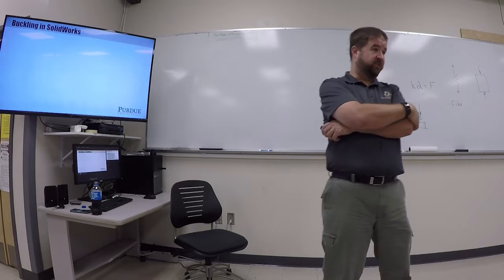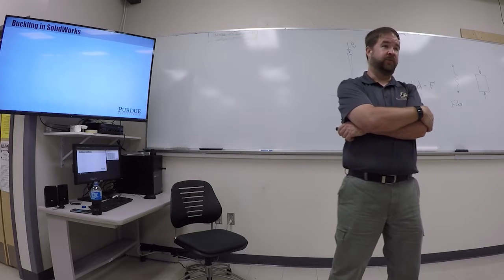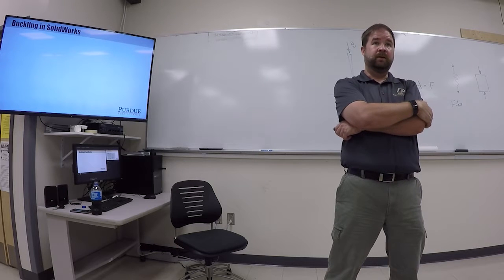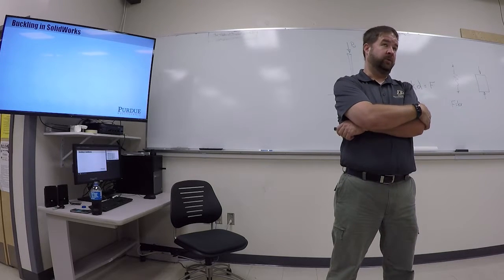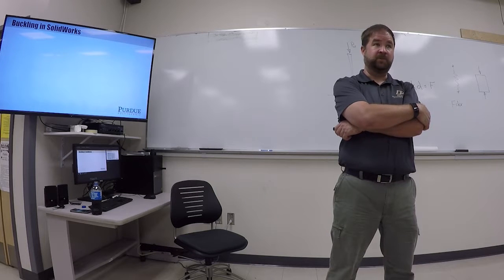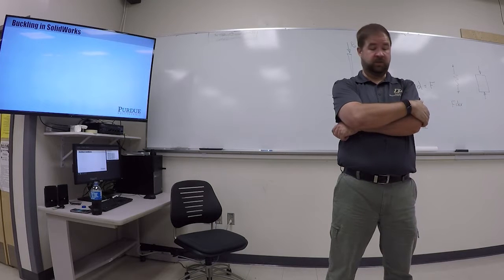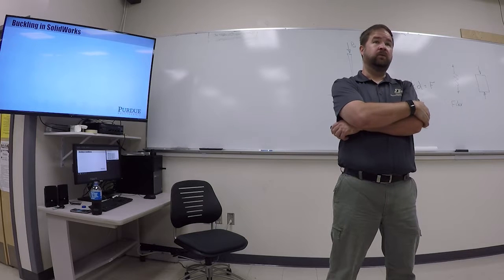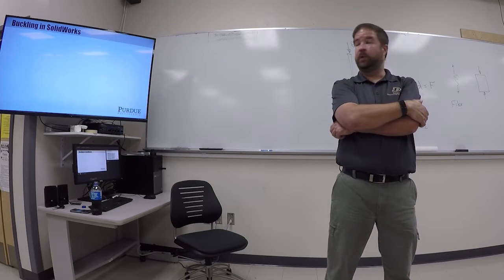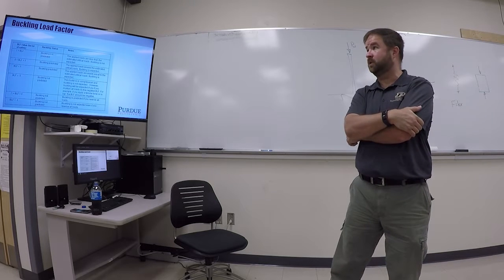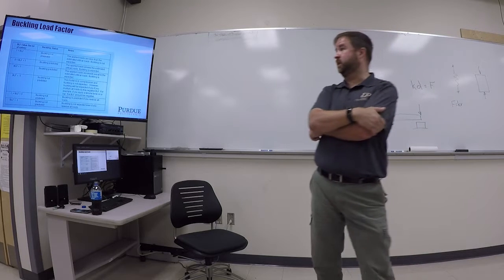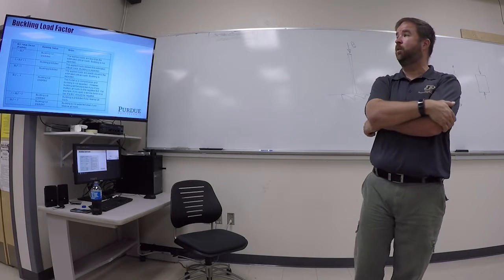There's a new type of study. The study is very similar to the other types of studies we've done in that you start the study, you give it a name, and then you define, or you probably have already defined, the geometry involved. You're going to tell it how it's constrained, whether it has fixed connections and so forth, what kind of loads are applied to it, and then you run the analysis. The output of the analysis is going to be what SolidWorks calls the buckling load factor. This is a screenshot straight out of the SolidWorks help.